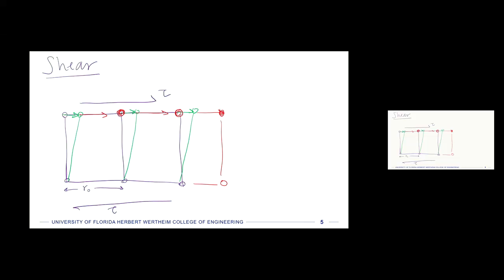And so this is considered when the lattice has slipped. And so you can see now that this is like a cascading event, right? So it can happen all at the same time, but let's say you have one location that's experiencing more shear than another. Well, that one's going to slip, and it's going to cause the next one to slip, and the next one to slip, and it's a cascading type event, right?